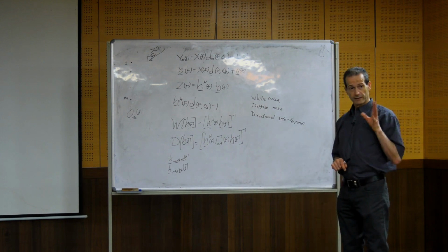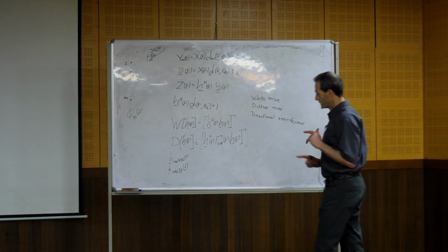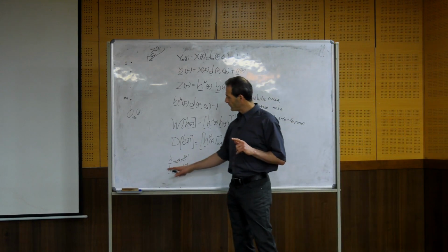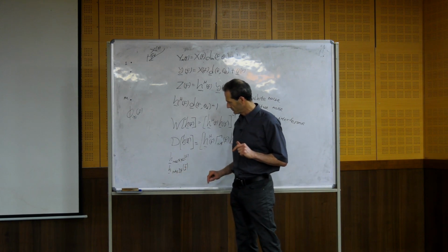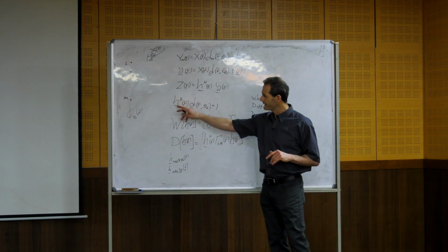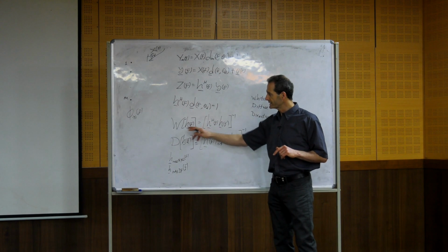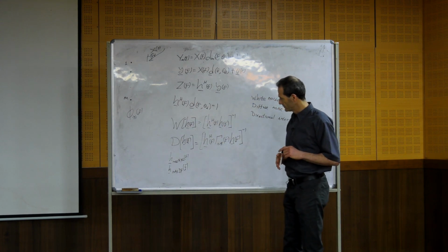Okay, so how do we do that? How do we increase the response to white noise gain when we design a beamformer that maximizes the directivity factor? So what we do, we add an additional constraint that the white noise gain will be larger than a certain value, a certain threshold.